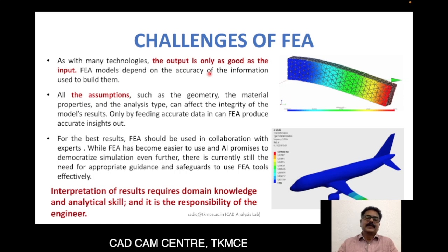For example, if I want to design a clamp to hold an air conditioner on the wall of my lab, we use a mild steel clamp, and we identify that it is to be fixed with 2 screws over here, and we give the material conditions, fixing property, those kinds of restrictions and all, and we conduct the evaluation by considering the weight of the air conditioner unit and all, and finally we will design the clamp. That means we will arrive at a thickness or the strain or the deflection of the clamp.